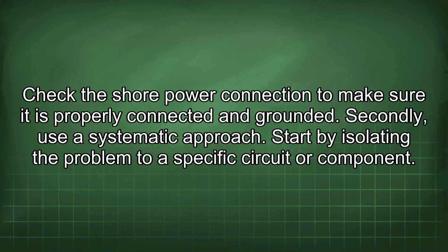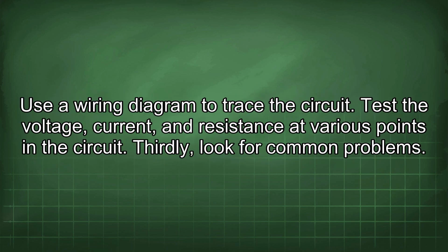Secondly, use a systematic approach. Start by isolating the problem to a specific circuit or component. Use a wiring diagram to trace the circuit. Test the voltage, current, and resistance at various points in the circuit.